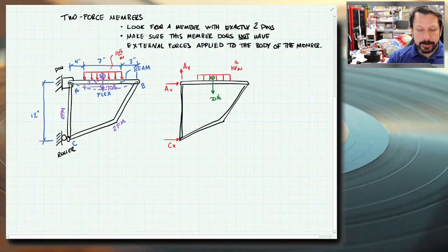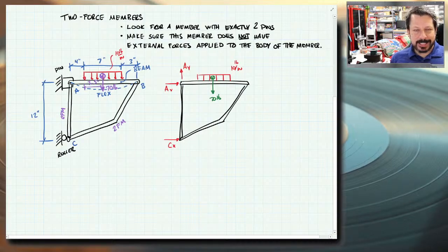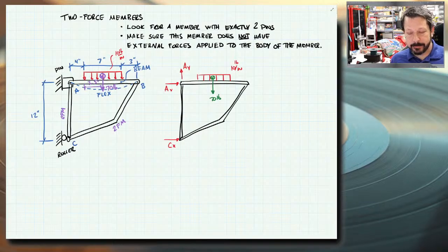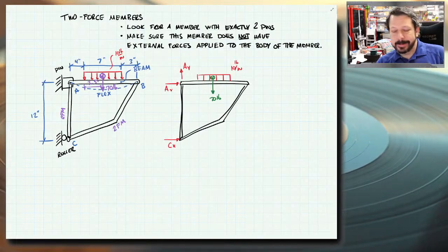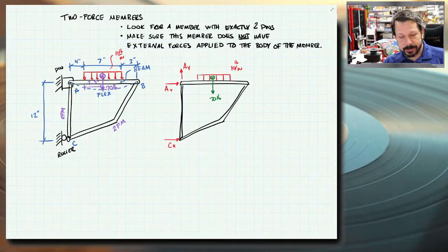So now I've got basically something similar to method of sections maybe. I've just got a rigid body and it has 3 unknowns, and I want to solve for those 3 unknowns. Again, it does follow the same rules where maybe you don't need to find the external reactions first. Maybe the thing you're looking for doesn't need them, but typically you will need them. And you have to solve for them before you start taking individual pieces of this and looking at individual pieces.